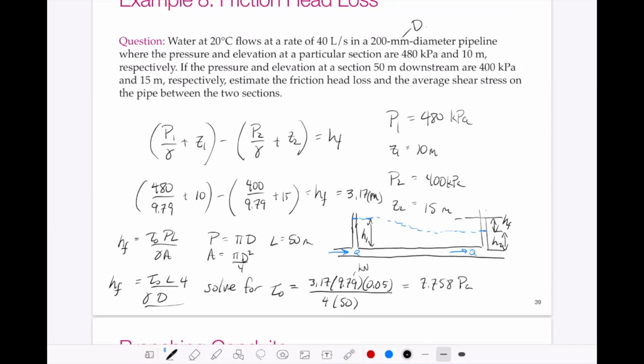So yeah, when we talk about the pressure heads, the hydraulic grade, this whole quantity here is H1. This whole quantity here is H2. So the Z values are not equal to H1 and H2. The Z values are the physical elevation of the pipe. The pressure head would be the sum of the elevation and the static pressure of the fluid flow.